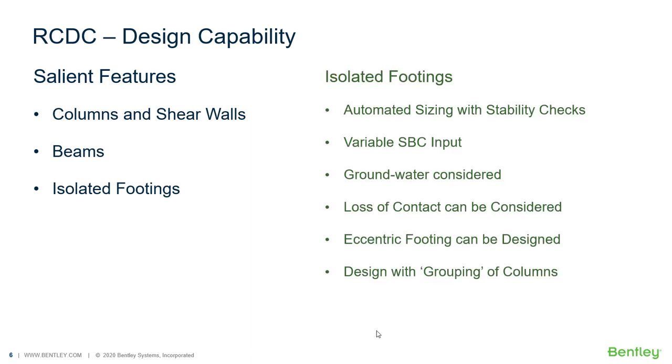Coming to isolated footings, RCDC can handle isolated footings with very simple basic design parameters. There is a logic to automate the sizing, including the stability checks. If users want, they can provide a variable SBC depending on the proportions L by B or depth or whatever. If groundwater presence is there, RCDC can handle the reduction in the weight for the pressure checks.